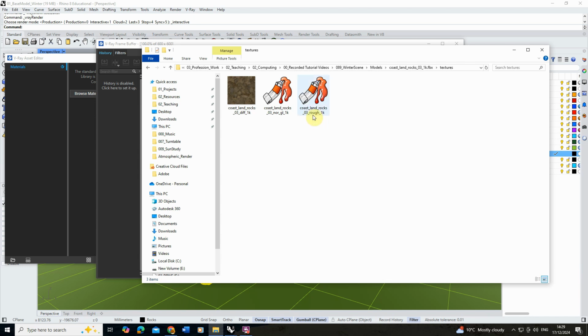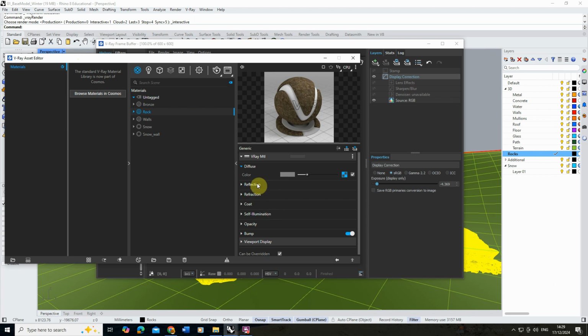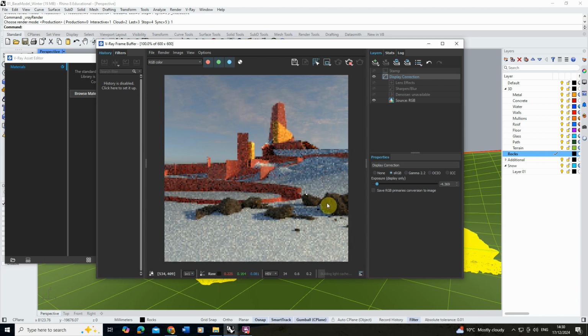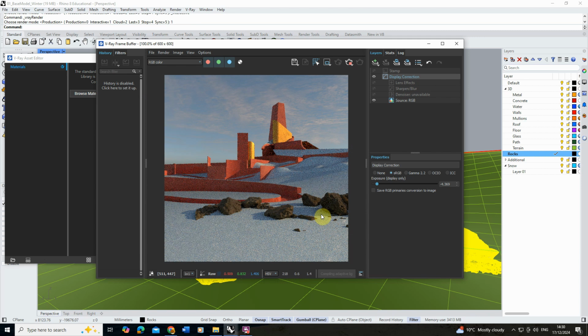Roughness we can actually use to set the reflective value of the object, but it does it in a slightly different way than reflection does. Roughness is essentially the inverse of that glossiness and reflection value put together. So you can always drop that map in and invert it if you want to as well. Something I usually do if I just want a quick fix is just paste the diffuse map into the roughness map, and it just gives you a little bit of values to work with there. There you can see it's just going to take the edge off this. It's going to be slightly shiny, but not much. It's just a very, very subtle texture we're adding in.